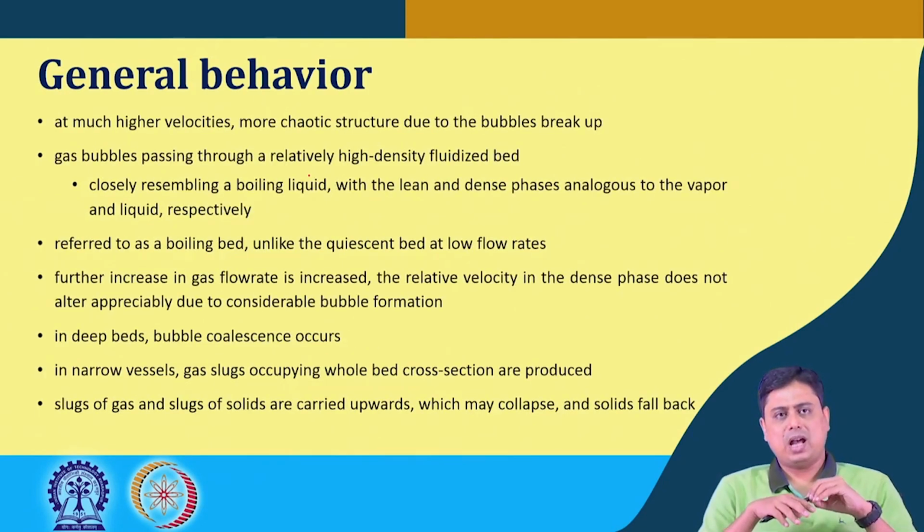Now, at much higher velocities, in gas-solid fluidization a more chaotic structure appears due to the gas bubble that forms inside the bed, that breaks up, and that creates a more chaotic motion of the particles.